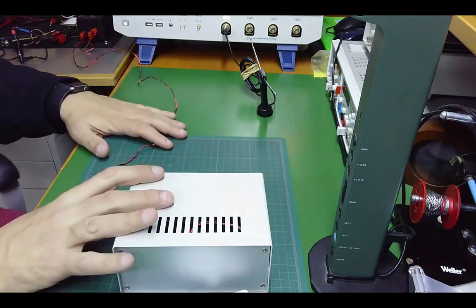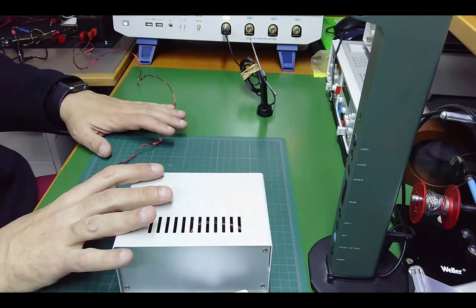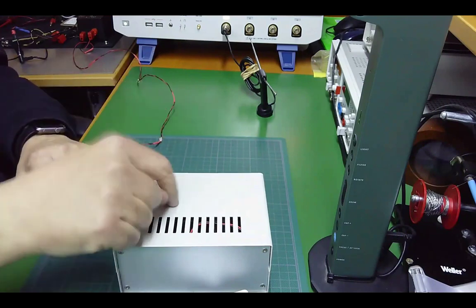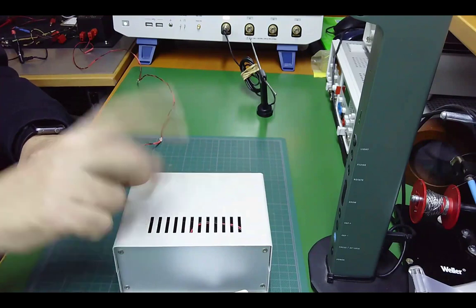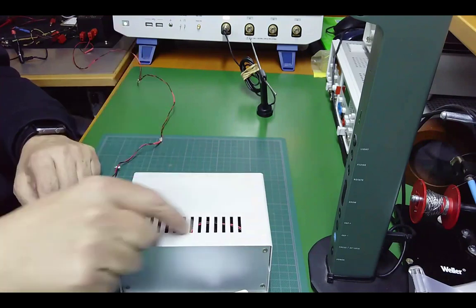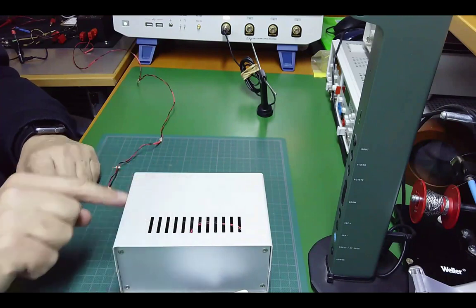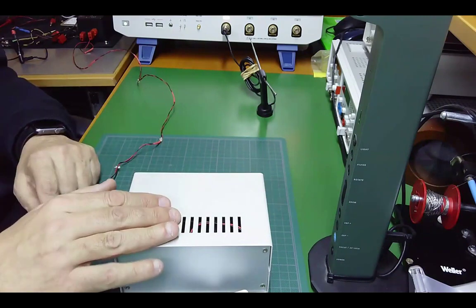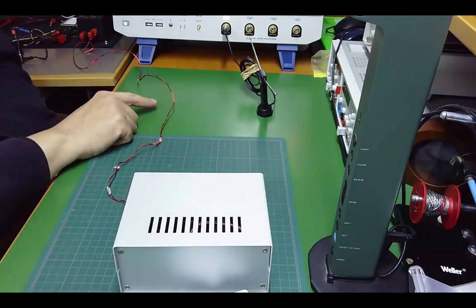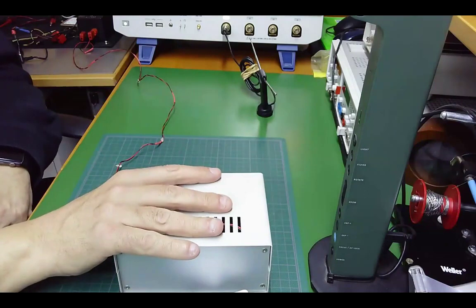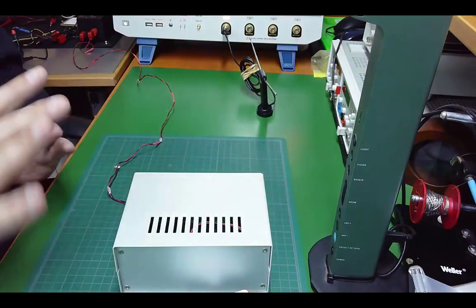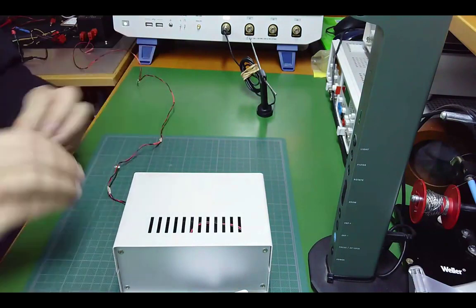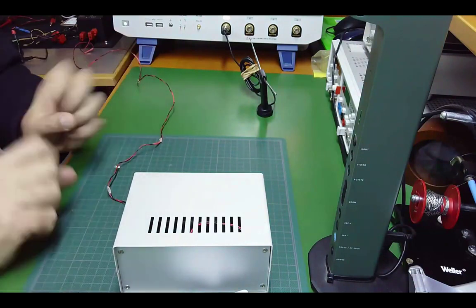So the first consideration you have is who is radiating this signal? You have several possibilities. One is the electronics inside of the product. Second is the slots or apertures you have in your enclosure, if it is metallic. Obviously, if the enclosure is plastic, you will have a lot of emissions. And finally, we have the cable. And to understand what happened here, and not always this is clear, perhaps you need to do some experiments to identify your possibilities.